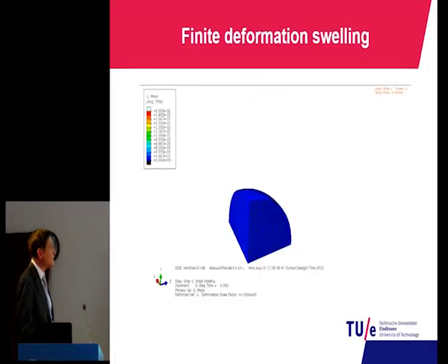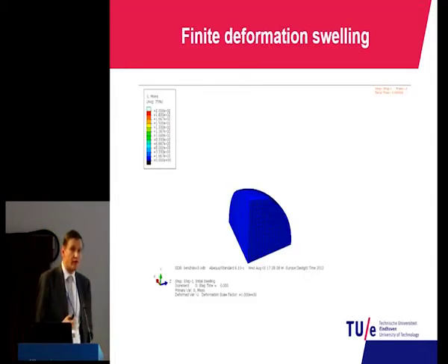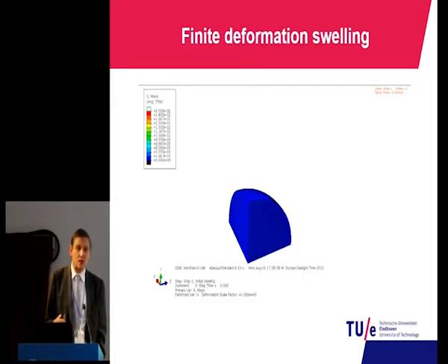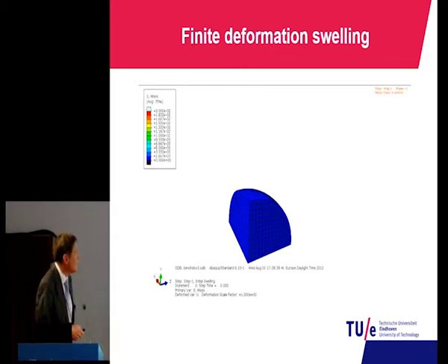Meaning, for instance, that gels can actually function as mechanotransducers. So they can translate mechanical load into electrical. Why? Because if this Mi appears explicitly here, the stress is going to depend on salt concentration, but if this E, this strain, appears in the electrochemical potential, the electrochemical potential is going to depend on strain, and we actually can show that this is the case.